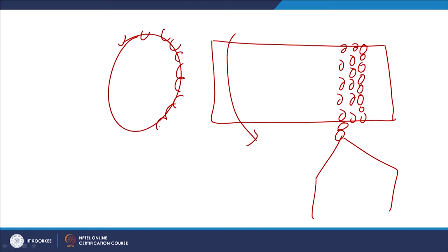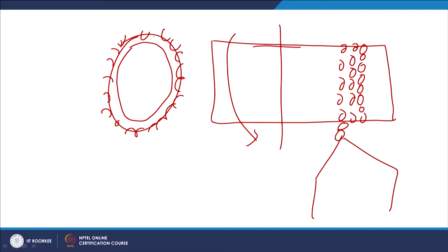In this scenario, if we try to see any section for the residual stress present, then the surface layers all around the periphery, wherever the shot peening has been done, will be under the residual compressive stress effect, while below that it will be under residual tensile stress. If we plot this distribution in the front view of the cross section, because this is a side view showing the circular cross section, it will simply be a rectangular shape for the cylindrical shaft.